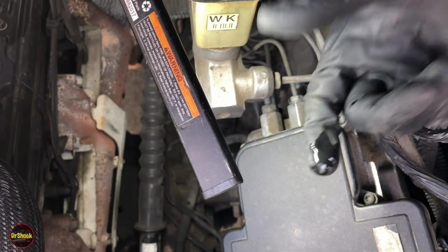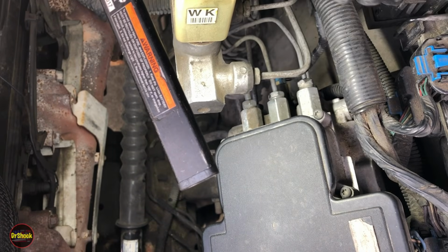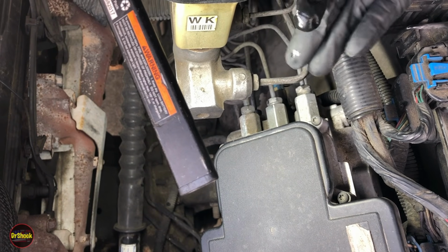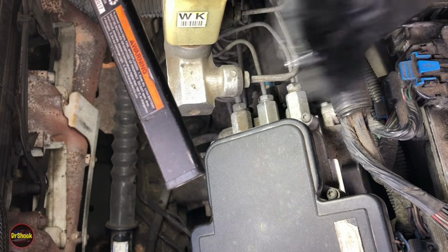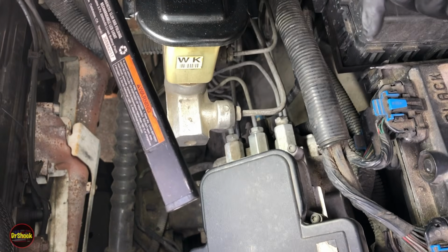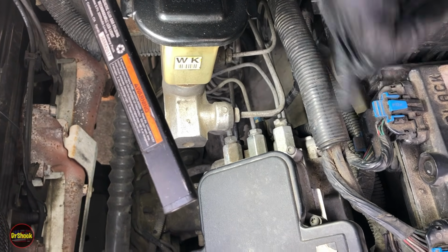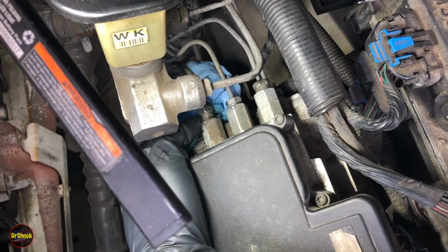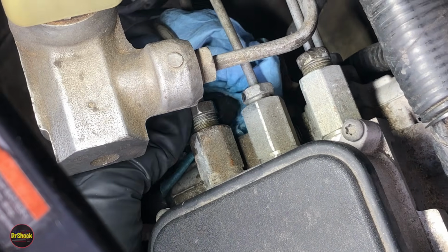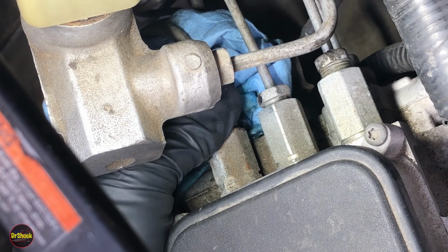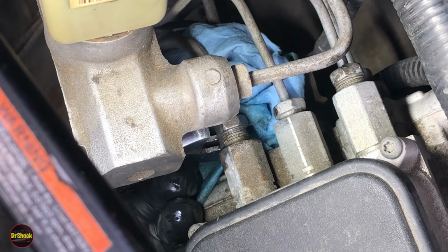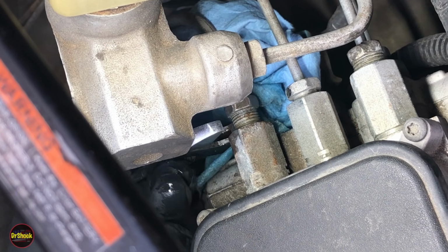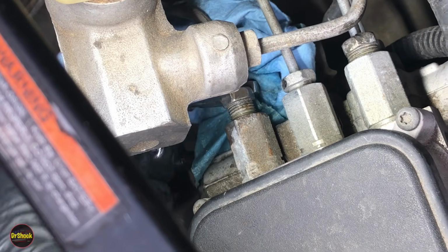What's going to happen is the brake fluid is going to start coming out. As soon as we get them loosened like that, we're going to get something under here to catch the brake fluid that's going to end up draining out of the master cylinder. Then we'll proceed to take the other two 13mm bolts out. They'll allow us to lift this up. All right, guys, we're working this one off here, just using a small crescent wrench when it gets too hard to turn by hand.